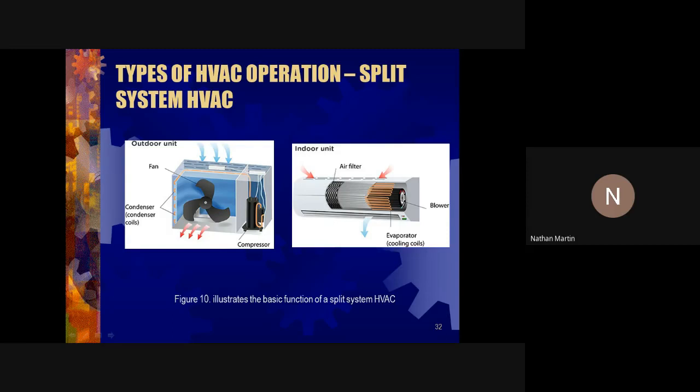Now, when people come out of the place, what will happen with the regular type AC is it will cut off the compressor, and the compressor will stop, and then the place will drop down to whatever temperature it will drop, and then it will chip in again, and it will have the starting current, and then it will build up back to the temperature where it then cuts out again.